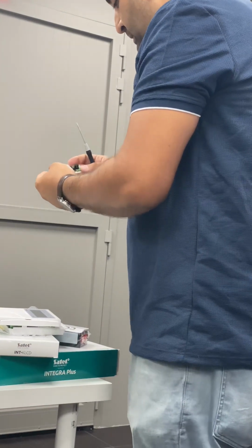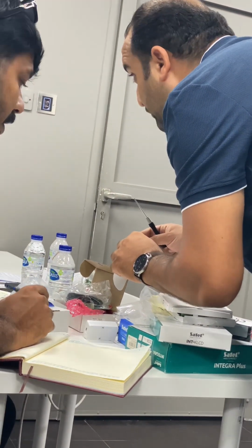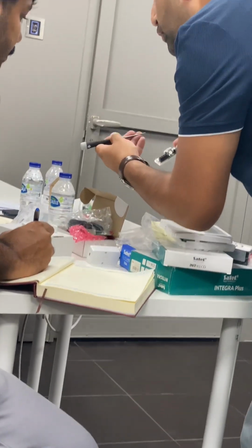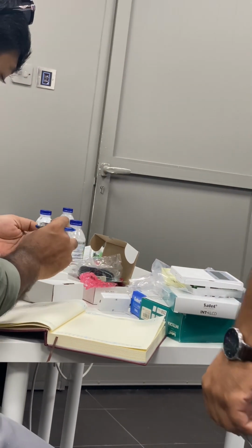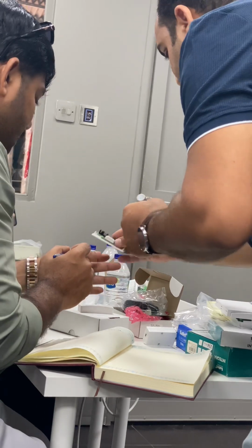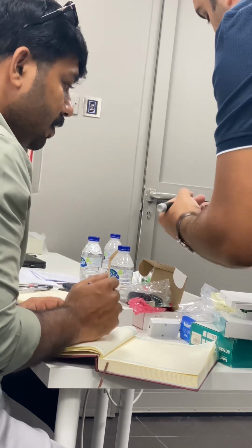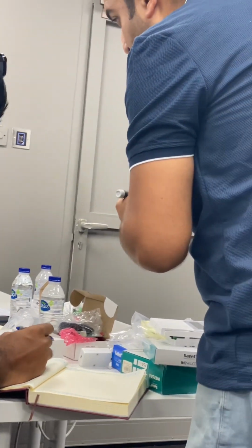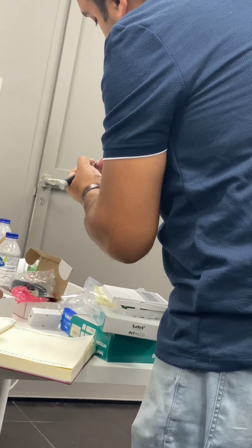So here, check this. You have two wires for alarm and two wires for the tamper. You have to take one of them to the zone and one of them for the camera. For the tamper, as we said, this one is not needed. For the alarm, this one. So this is your device. I will show you every device and what the connection is for it. In the first device, this one is a door contact. You can take the first one to the zone.